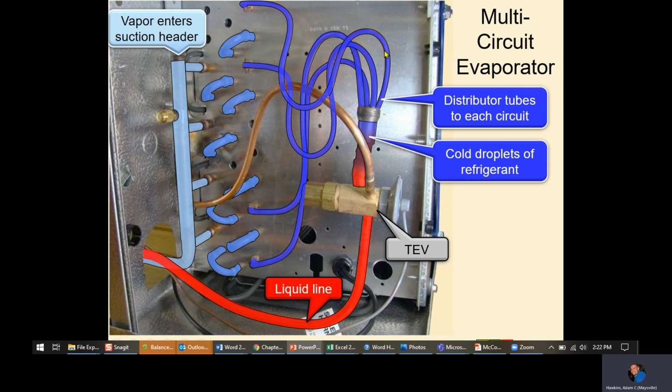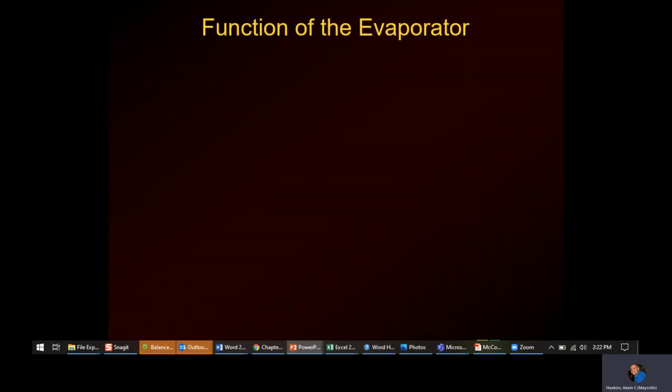And while I'm on the subject, a lot of people will call these capillary tubes, and they're actually not. They're distribution tubes. They're distributing refrigerant to the evaporator or to the condenser. The term capillary tube actually refers to a type of metering device, but they do look a lot like a capillary tube. So these can get stopped up. These are really bad for rubbing holes in each other to where you'll have rub outs for leaks. So this is a good place to check for leaks. If you have one of those that's underfeeding, it could be because you have a restriction in one of those.